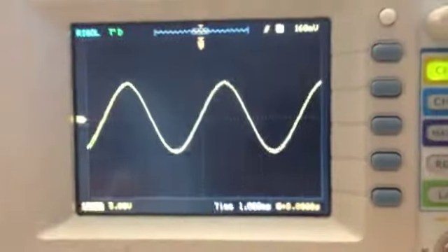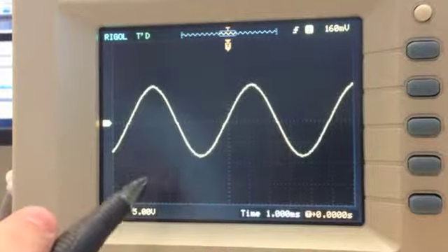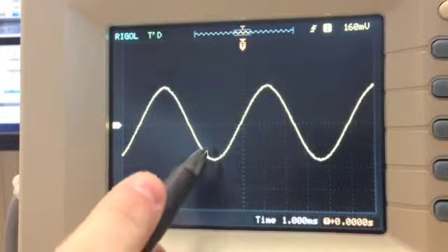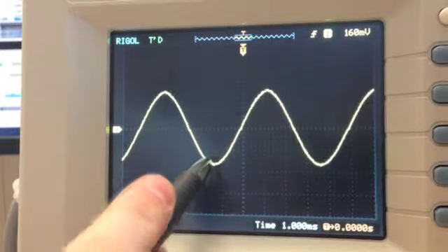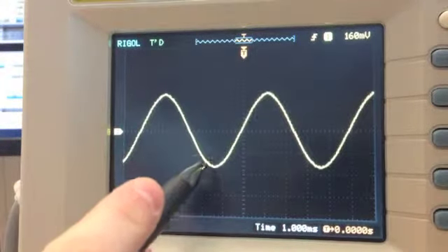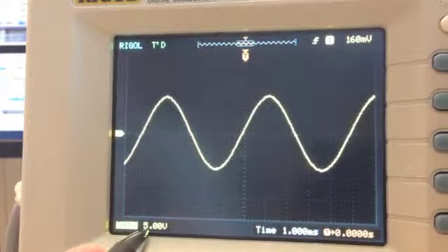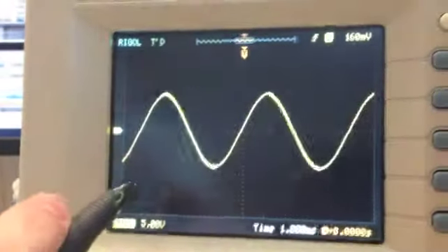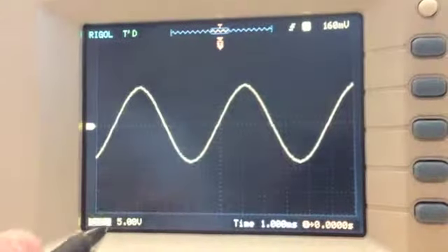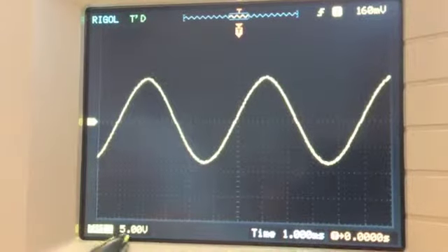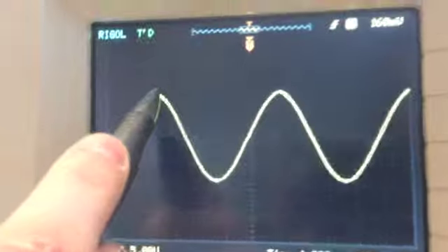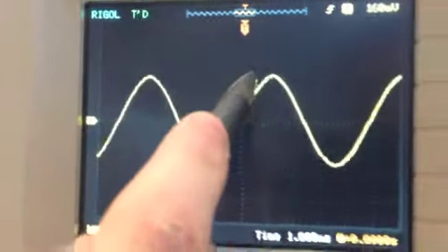I think that's it. Alright, to measure the old school version on the digital oscilloscope, for the volts peak to peak, we would count the blocks from the minimum to the maximum, and then whatever we get, we would multiply that by 5, and that's for our volts peak to peak. And we are in channel 1 right now, but you do the same thing for channel 2, as long as you go by this number that you multiply by. And then for the time, you would measure each block and then multiply that by 1.